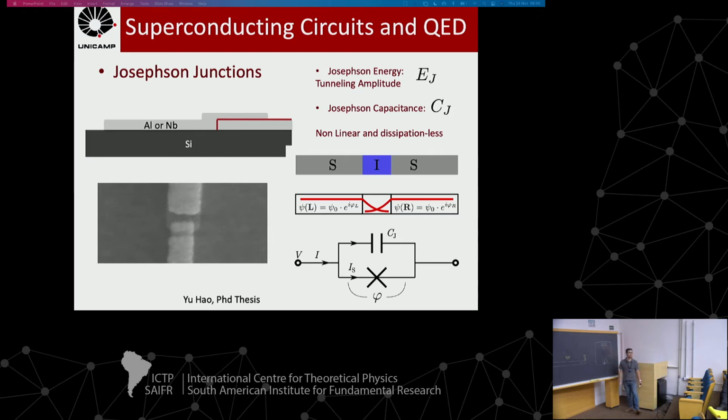So if you want to make a shadow here, what do you have to do? You cannot change the direction of the atoms; it's really hard to move everything here. So you move the sample. You change the angle of the sample relative to the direction of the aluminum atoms arriving here.